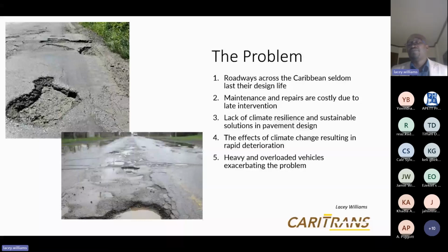And when you do surveys, for example, axle load surveys or surveys that involve the weighing of trucks, we then understand that, wait a minute, even if I were to design my roadway for climate resilience and do whatever maintenance program, if I do not spend the time and effort in arresting the issue of overloaded vehicles, then we may be significantly reducing the pavement life.